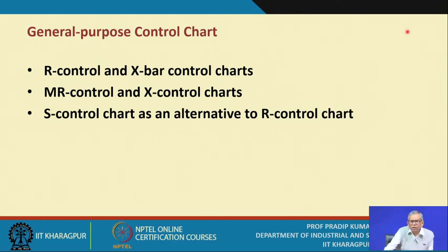As soon as, suppose, the value of n, that means the sample size, is greater than 10, you may conclude that the range cannot be a good measure for dispersion. Okay, it is an inaccurate measure if n or the sample size is greater than 10, right? So obviously in such cases you opt for the standard deviation control chart. So this is point number 1 to be noted.